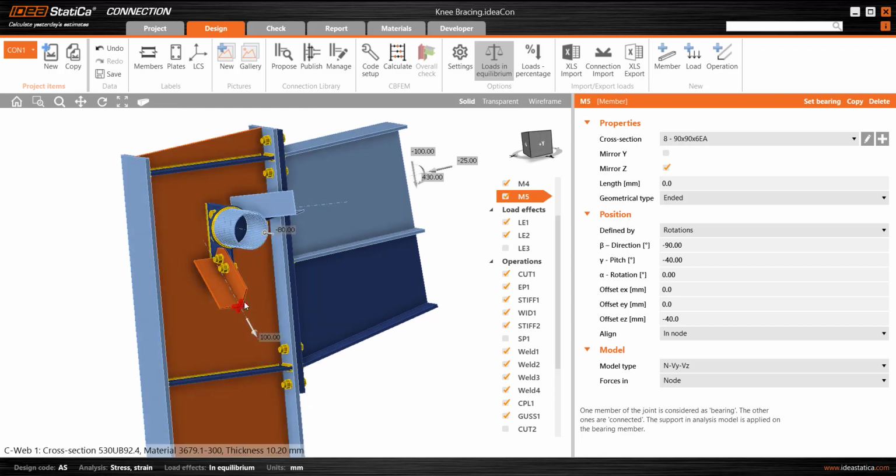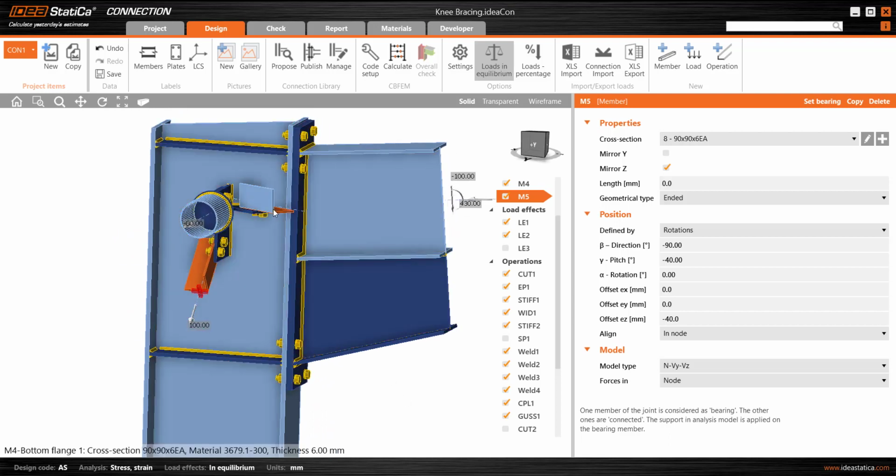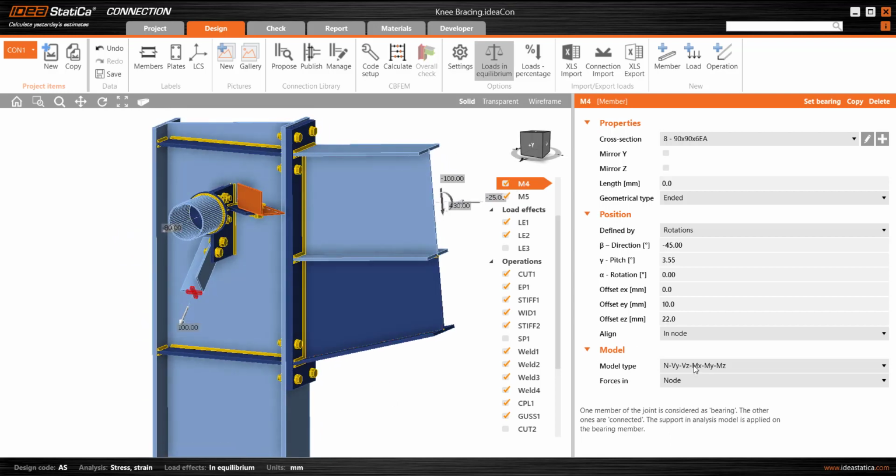So this will simulate, in a way, that the member, the angle, cannot freely rotate about the gusset if it is flexible in a through thickness bending sense, which it will be to a point. So the angle is connected to steelwork at the far end, and there will be a reasonably good resistance to this type of lateral rotation and movement. So this is a reasonable model type, I believe, simulating the conditions in the actual structure. So I'll do that also for this member here.